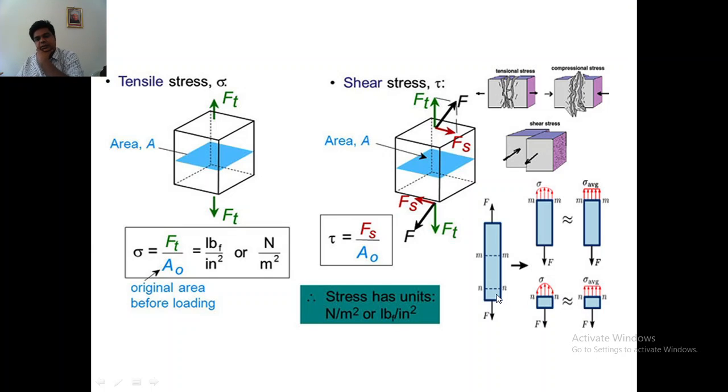And here also you can see the tensile load is applied on the bar at cross section NN. If you take the cross section here, the tensile load is applied, and this is the internal resistance or the reaction force inside the material. So when you apply external force F, the material also will react internally. Inside it will show resistance to the applied force.